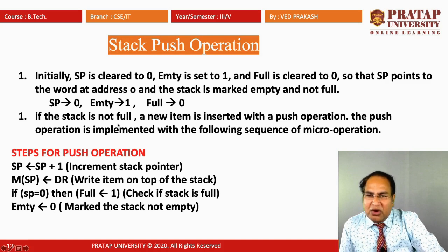If the stack is not full, a new item is inserted with the push operation. The push operation is implemented with the following sequence of steps. First, we have to increase the value of the stack pointer by 1. So SP goes to SP plus 1, and after getting this increment, we set M[SP] with DR. DR is basically the data register through which we insert the data in the stack.